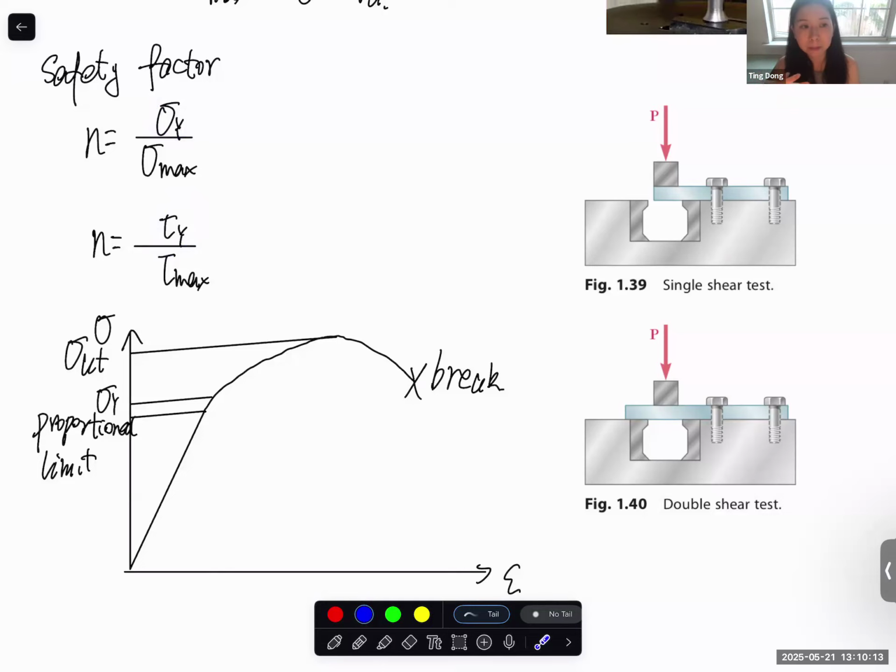Let's say you make a table for yourself. You probably don't mind about plastic deformation of the table. You're probably just concerned about when it actually breaks, right? So it's not always the situation, but most of the time we consider yield strength. In some textbooks, they use loss of function strength, of the maximum strength. That is a more accurate definition, but I think in our class, this should be enough because a lot of the time we just have the yield strength.